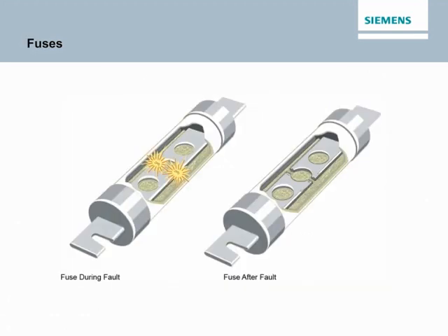An overcurrent protection device must be able to recognize the difference between overloads and short circuits and respond in the proper way. Slight overloads can be allowed to continue for a short time, but as the current magnitude increases, the protection device must open faster. Short circuits must be interrupted instantaneously. Overcurrent protection can either be accomplished with a fuse or circuit breaker. Circuit breakers will be discussed in detail throughout this course, but first, it's useful to discuss how a fuse operates.